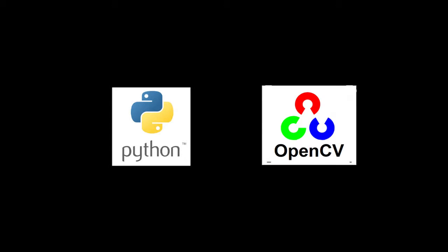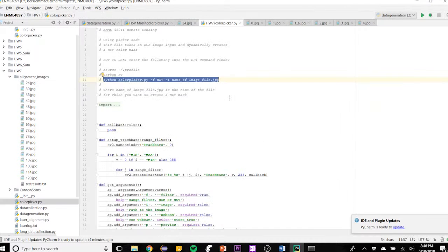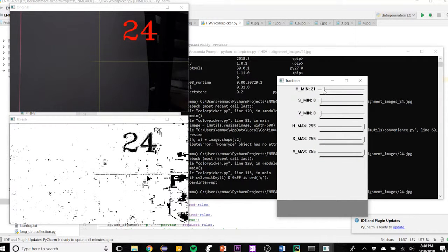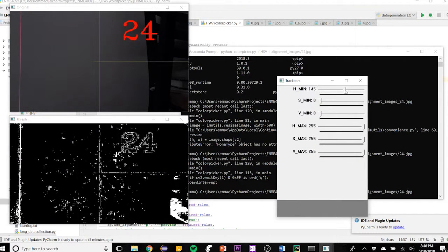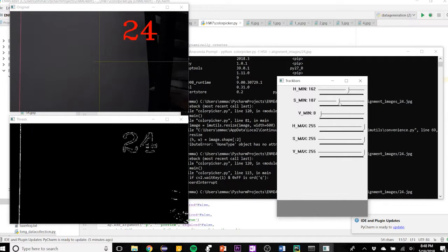This Raspberry Pi runs Python scripts that use the OpenCV library. After I take pictures of my target, I'll need to isolate the red laser light in my images to effectively process my data. Essentially, I need my data processing script to only look at the laser light reflected back from my target and not at any light coming from ambient sources, since any other light that doesn't come from the laser will generate noise when I'm trying to create a 3D point cloud.